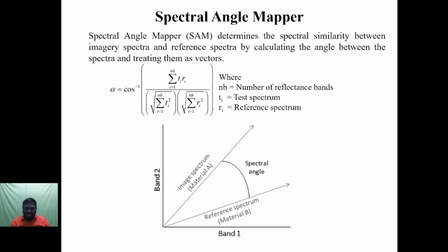We need to select the particular bands only, otherwise it will give a very large amount of information, which is not necessary now. We need to identify the limestone band. That limestone signature will give a very high level in 1200 to 2500 nanometer. For that, we will get it from the SWIR region only.